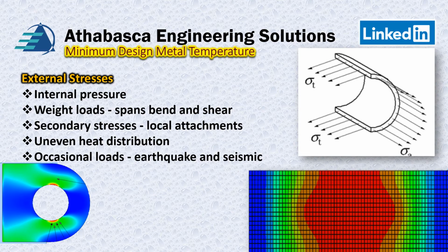They can be self-limiting type stresses, where if the part flexes, the stresses drop, or non-limiting, like internal pressure doesn't matter. The forces are always there. Those are all factors that one needs to consider.